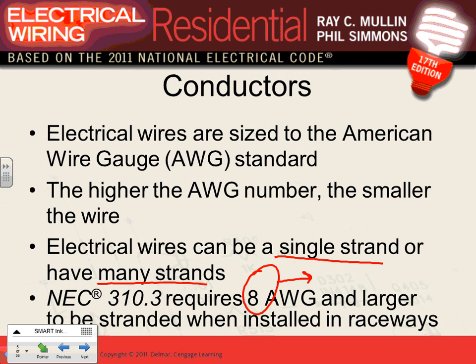If you are to put size 8 or larger in a conduit, it must be stranded. Only in a conduit. If it's not in a conduit, it doesn't have to be stranded. Typically, conductors larger than number 6 are stranded anyway. They make them stranded, larger than number 6, because it's easier. Everybody knows stranded versus solid, so here's a solid conductor, right? That's completely solid, stranded, and they make them a bunch of strands over here. That's your conductor.